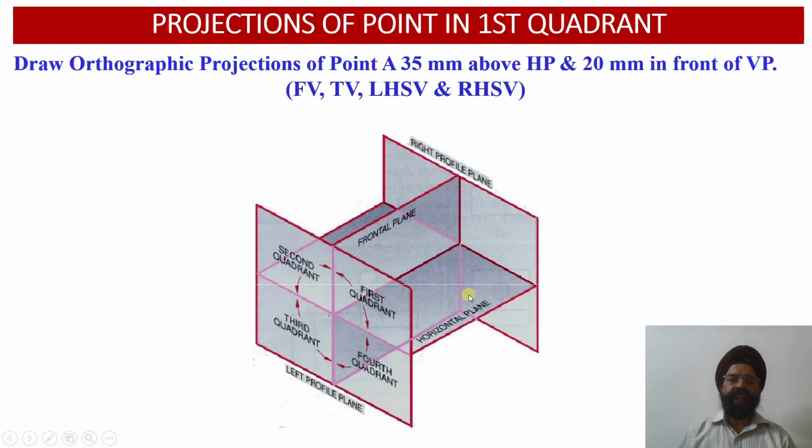Now here we have got the horizontal plane, the vertical plane and the profile plane. And we know that the projections which we are going to obtain upon these three mutually perpendicular planes of projection are going to be available to us in three mutually perpendicular directions. In order to obtain the two-dimensional orthographic projections onto a single plane, we have to carry out the rotation of two of these three planes.